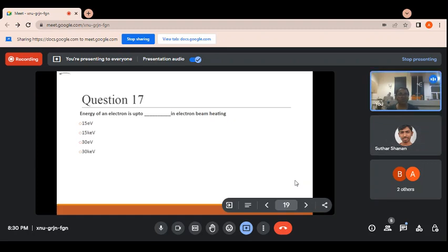Okay, but tell me now, if you want to transfer an IDE pattern, and the pattern is in dark shade, where the chromium is, and the remaining background is transparent, so what type of mask is it? The background is transparent, only the structure you need is in dark.